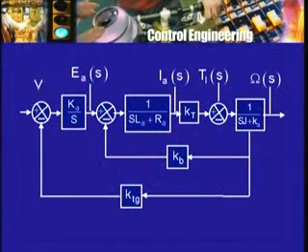So in the block diagram now I am going to show, starting with the reference voltage, the plus minus difference device. The output, of course, that is to be expected is omega s, input is the reference voltage ER of s, and between the two you have the K tachogenerator coefficient, because that feedback we are keeping. The output of the difference device goes through an amplifier combined with an integrator. In other words, 1 by s is the integrator action, Ka is the scaling action, and if Ka is greater than 1, then we are amplifying the output of the integrator. This output of the integrator becomes the applied voltage Ea of s.